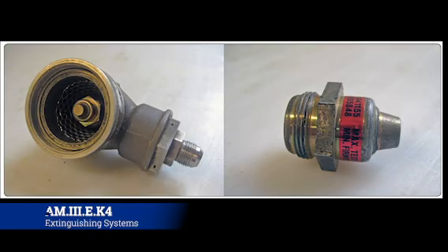Now, part of the fire extinguishing system will also be to close off all the fuel to the engine, which then helps not only remove the potential agent that could be on fire, because it's fuel, and it's very likely that it's at the very least contributing, if not the primary thing that's on fire. But it also keeps the engine from running, which in theory will also kill electric power. It potentially could remove any hydraulic power if the hydraulic pump is the one that caught on fire or something like that, and it basically stops the situation from progressively getting worse due to that.